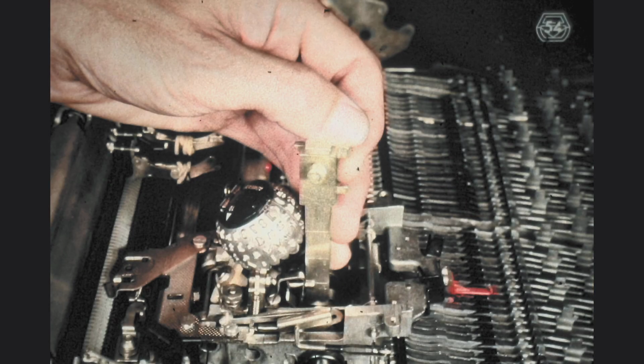The final adjustment in our sequence of fine alignment adjustments deals with the motion of the detents. When the detents are engaged, we must be sure they are fully seated between the teeth of the tilt ring and the type element. When they are disengaged, we also want to be sure they clear the teeth by a given distance. The source of motion for the engagement and disengagement of the detents is the detent cam. We have seen that the cam follower transmits the motion to the detent actuator, the actuator transmits it to the tilt detent, and the tilt detent transmits the motion to the rotate detent.